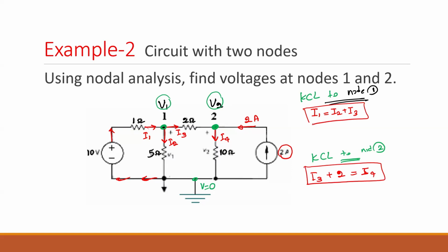How do we write I1 now? Where is I1 starting from? These all are zero. This whole thing is zero. They are wires, so they are flexible. So that whole part is connected at one point. So it is starting at 0 volts and minusing minus 10. Why? You are going into the negative side of 10, so you're minusing all the voltages on your way. Then you are minusing V1 divided by 1, where 1 is the resistance here. So that will be 10 minus V1.